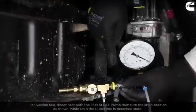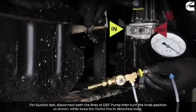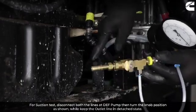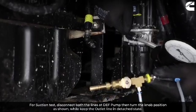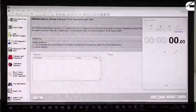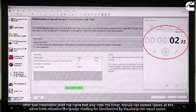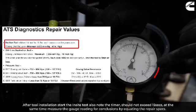For the suction test, disconnect both the lines at the DEF pump. Then turn the knob position as shown, while keeping the outlet line in a detached state. After tool installation, start the INSITE test. Also note, the timer should not exceed 15 seconds. At the same time, measure the gauge reading for conclusions, by equating it with the repair specs.